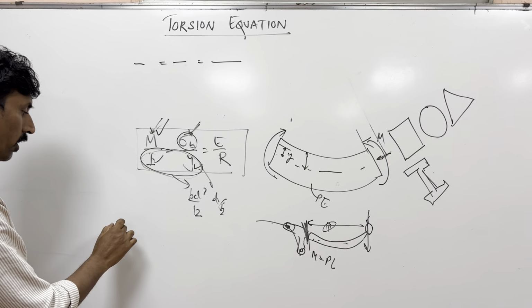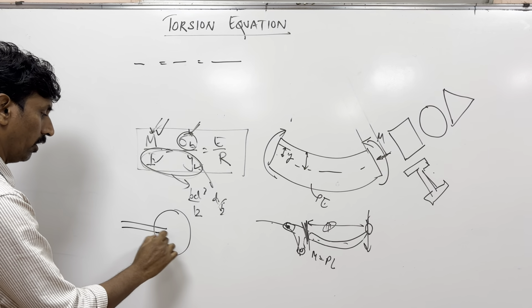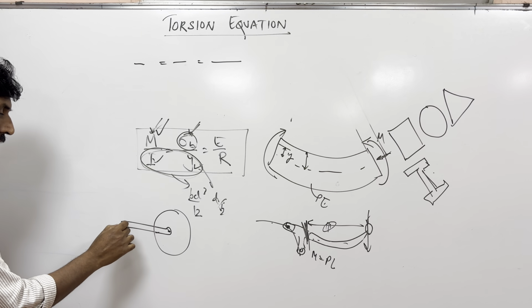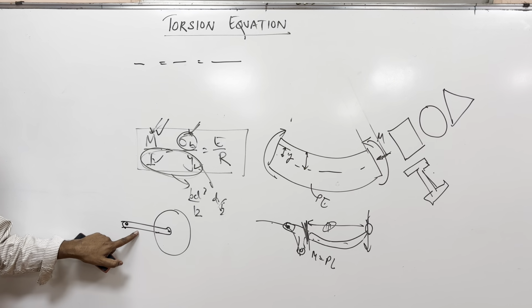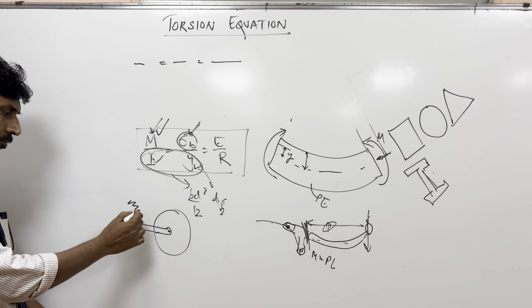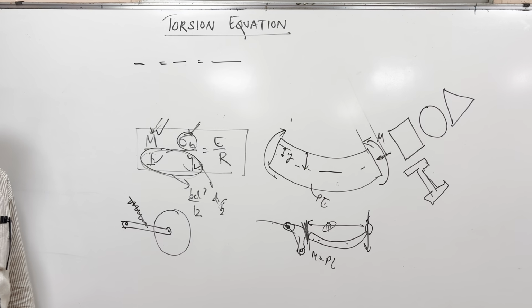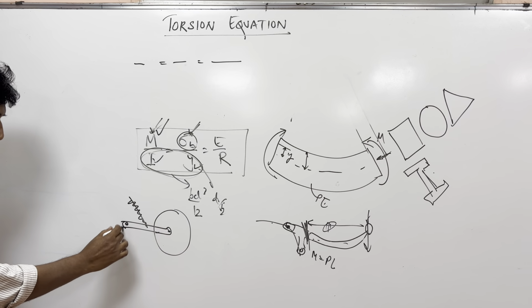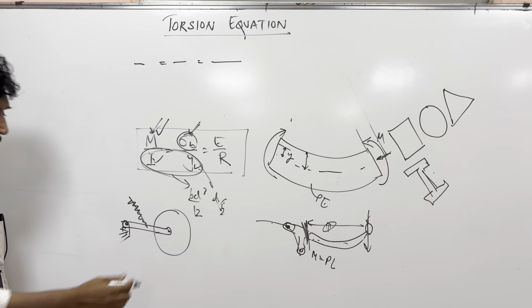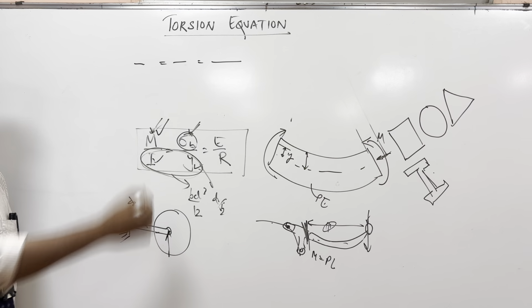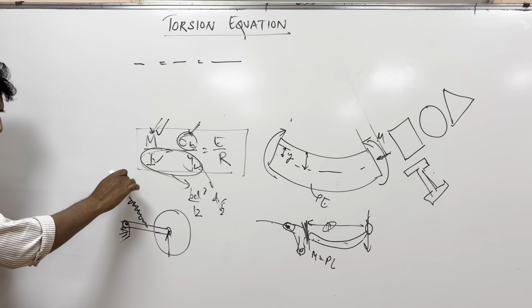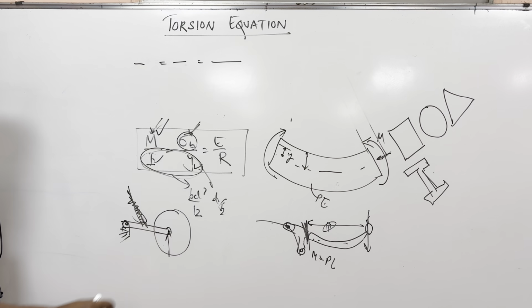Now what would be the type of load on this rear wheel? The rear wheel is held on this. Now what is this component called? Swing arm. So on the swing arm, you will have a spring attached here. It is hinged here, and the wheel is applying a load like this, and there is a load coming from the top because of the weight of the vehicle. It's again like a beam, and it's under bending.